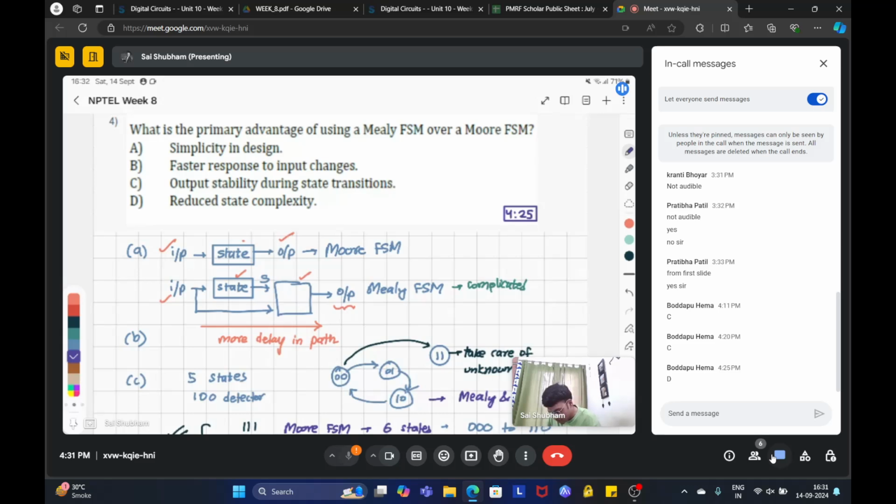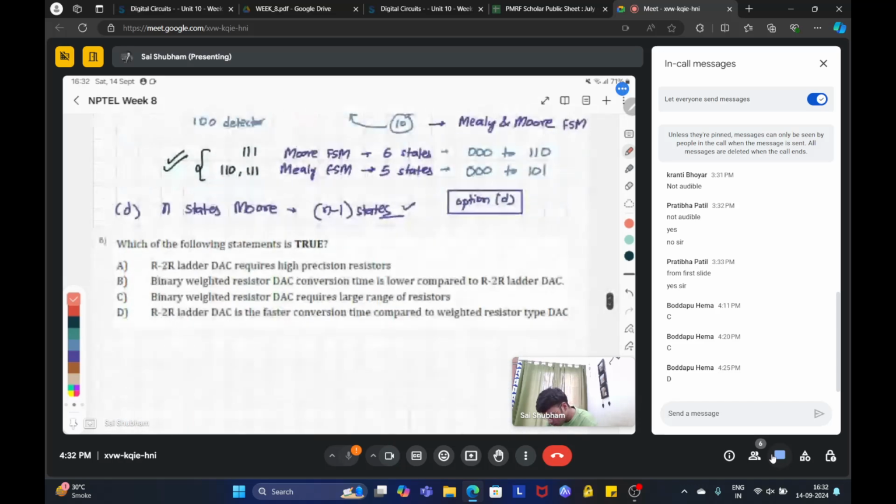So whenever there is a straight transition, your counter grows, suppose there is a 2-bit counter. It will go from 00 to 01, then 10 to 11. So in this case, you will see that in this transition, 0 also changes from 0 to 1 and 1 also changes from 1 to 0. So this can lead to some glitches. So instead of this, we use gray coding. That can make sure that only one state changes at a time. So that can be done for this.